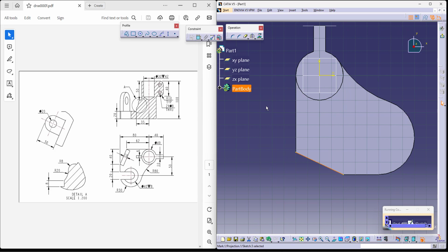It's very easy. Instead of creating perpendicularity and complicating the process, I'd like to use an offset command, using which I can directly offset the sketch to a certain distance and then add the material. This is around 10. Now I can simply close the lines rather than complicating it again. Similarly, I can close the lines here as well and add the body. This is 10 as shown in the drawing.